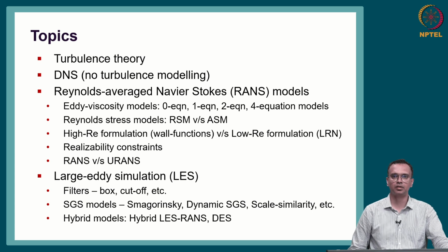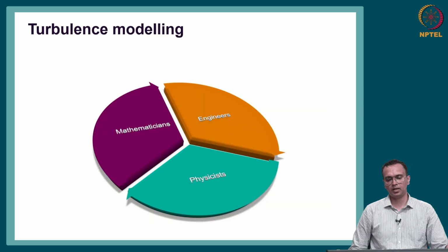In addition to this, of course, there is the large eddy simulations or LES. So here we look into various filters and their impact on LES, as well as the subgrid scale modeling, various options that we have. And also we will briefly touch upon the hybrid LES-RANS models or the detached eddy simulations and so on.